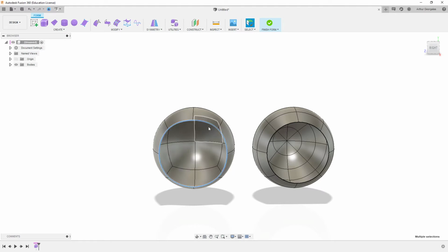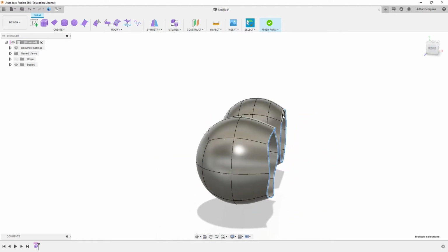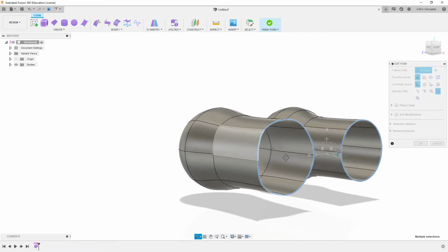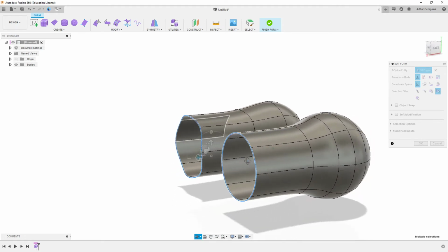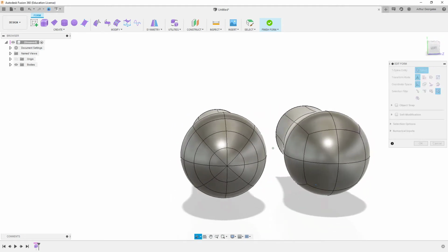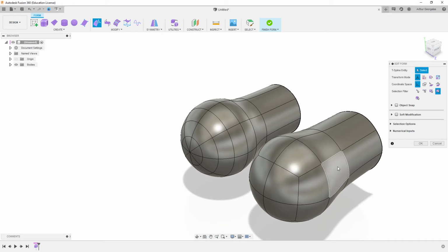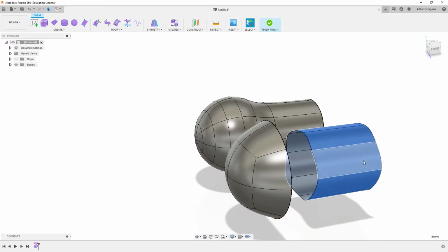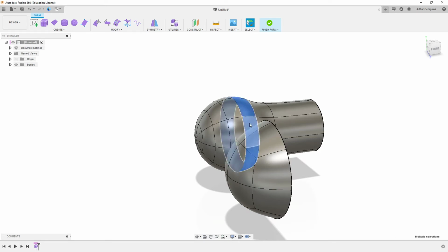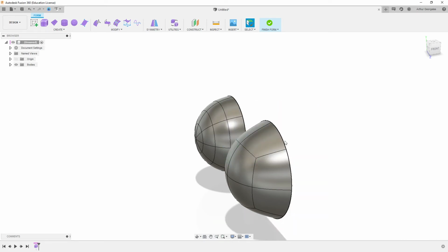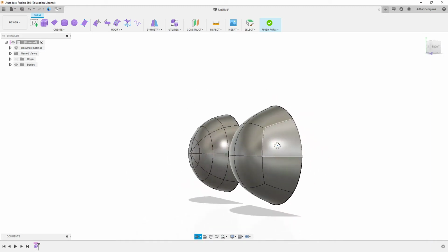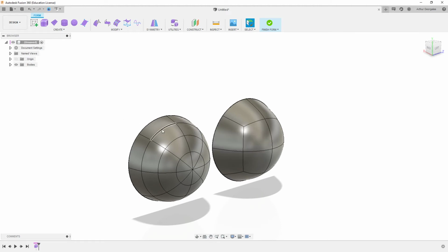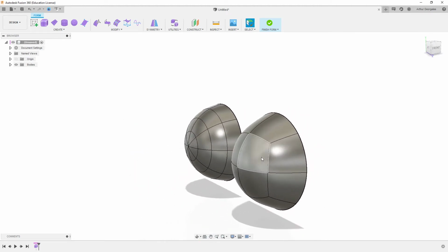It's easier to manage. And so if we edit these and pull them out, we can see we're still achieving that rounded shape. This can work, but for some things where you actually want really good control, it can just be super useful to go with the quad ball instead. I would generally recommend the quad ball because what you can actually do is really easily blend this into a cylinder you've created, whereas this is a lot more complex.